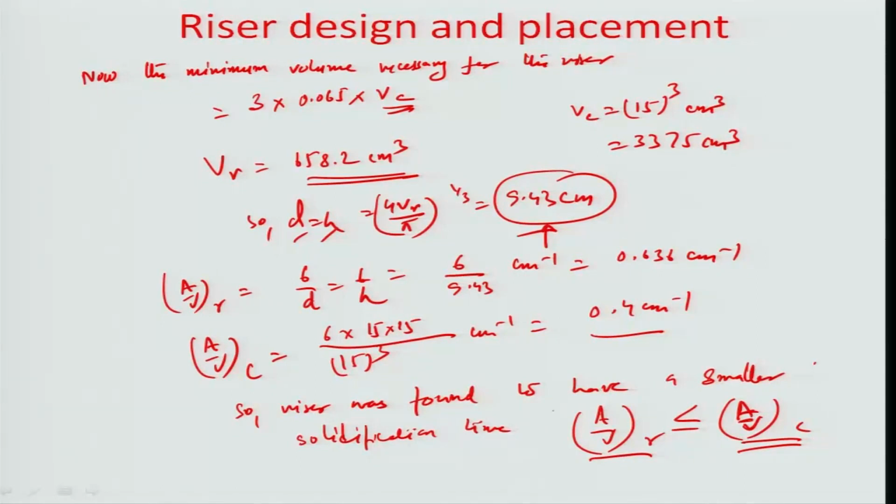So, we have to do a force fit, and we try to do that by forcing the volume by area ratio to behave in this relationship, so that the time of solidification of the riser, which is actually proportional to the volume by area of the riser. Okay. So, in that case, the time of solidification of the riser should be more than the time of solidification of the casting. Okay.